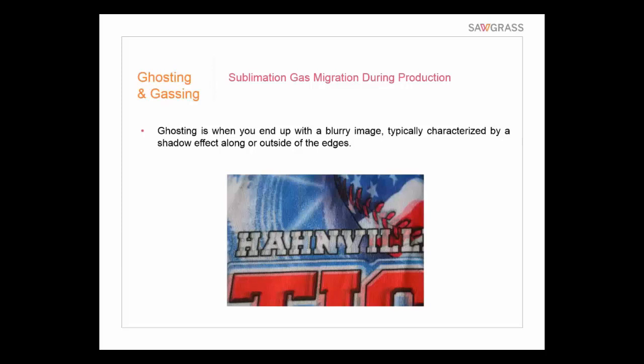So when we open the heat press, it releases the pressure and then it decompresses, and in that case the paper starts to lift upwards. In fact, there's almost like a vacuum effect when we open that heat press. It tends to want to lift the paper off the surface. It doesn't have to lift it much, okay? It might lift only a couple of millimeters up, and then it falls back down. So it starts going up with the platen, falls back down, but in that falling back down, there's a good chance that it caused the ghosting that you see here.